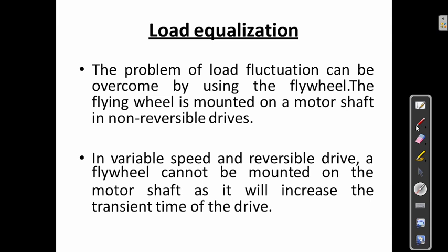In variable speed and reversible drives, the flywheel cannot be mounted on the motor shaft as it will increase the transient time of the drive.